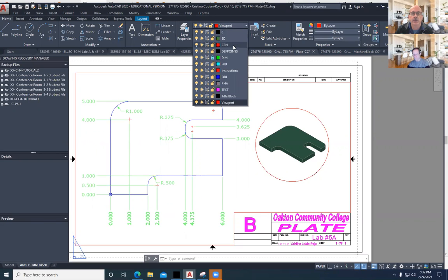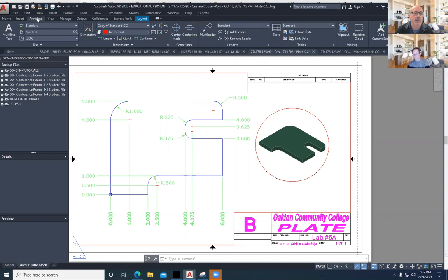So as you start to create these drawings, you want to make them correct. I'm just going to check the room real quick to make sure I didn't miss anybody. Looks like I'm okay. So set the dimension layer, and then if you use a center mark, if you click on an arc, you'll get a center mark for that.